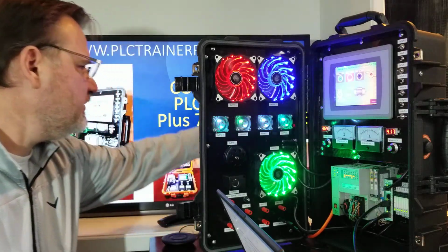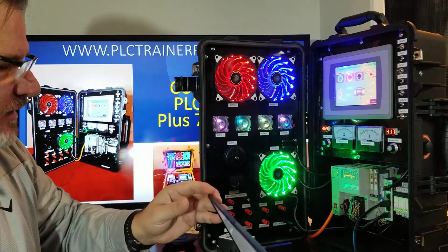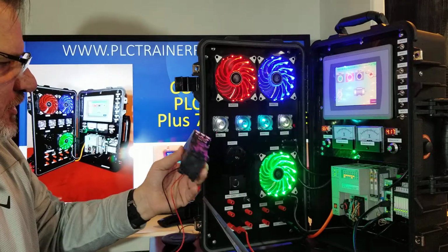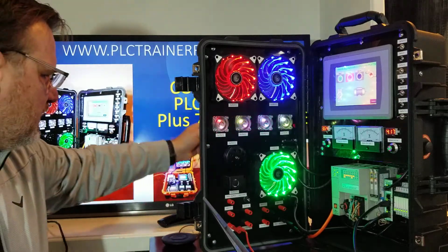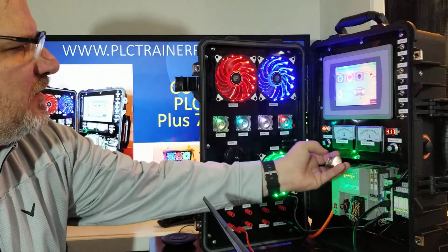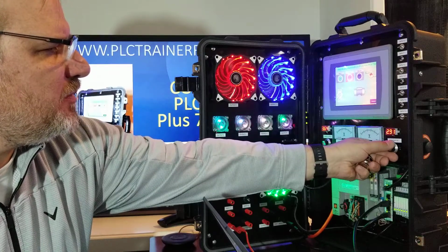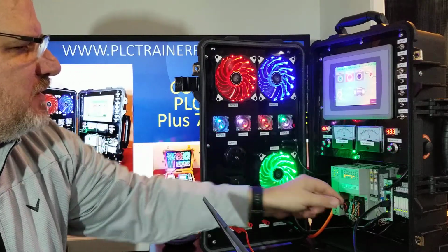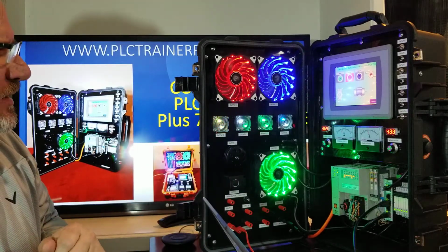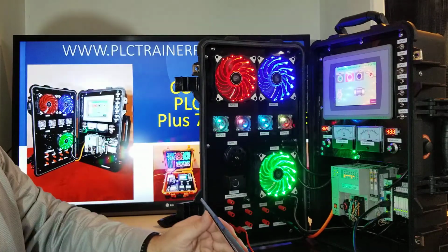Also, we'll illustrate with a contactor. There are some banana connectors here that we can use to simulate some outputs with the program. So let's go ahead and get started. We've got a little pot, the same as these here, that can show you the 0 to 10 input. It can simulate a signal such as a level control, speed control, or conveyor speed up and down as an input to the PLC.